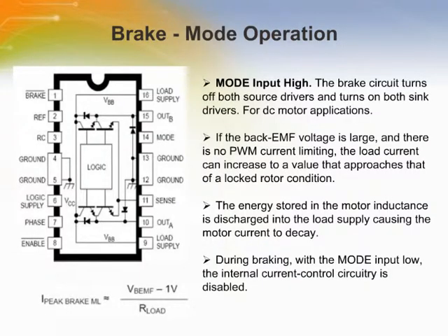Brake mode operation. When a logic low is applied to the brake input, the braking function is enabled. This overrides enable and phase to turn off both source drivers and turn on both sink drivers. The brake function can be used to dynamically brake brush DC motors.